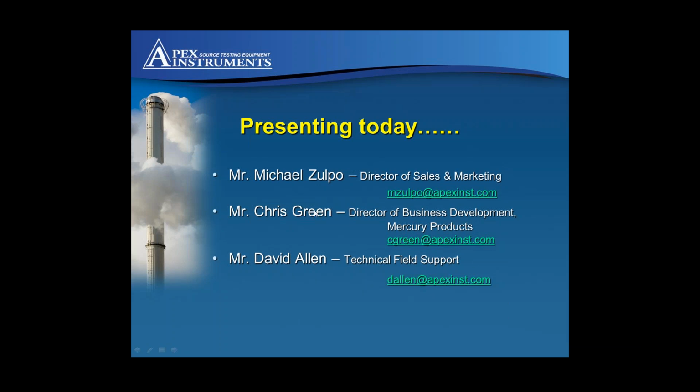So I would be using that. If they okay that petition, then you're saying that when we test under Method 4, that's the value we use for moisture? Exactly. You could do a gravimetric test on Method 4 from the moisture that's collected during, say, a 7-day sample run. We have moisture knockout bottles in our system that collect the moisture we've removed from our gas conditioning system, and you'd be able to use that instead of a secondary device or your default value to do a gravimetric Method 4 and report the actual value that way.